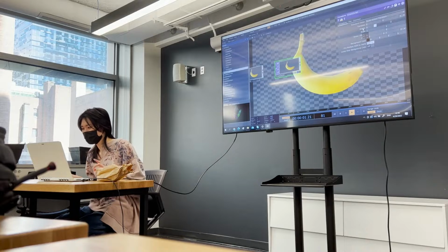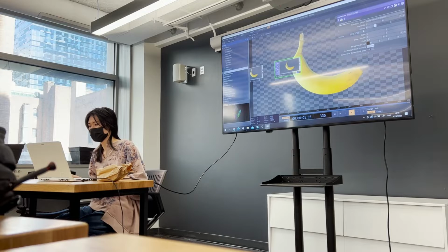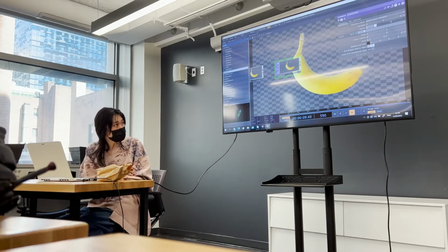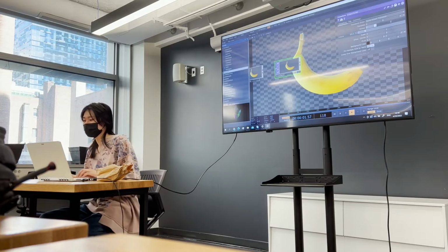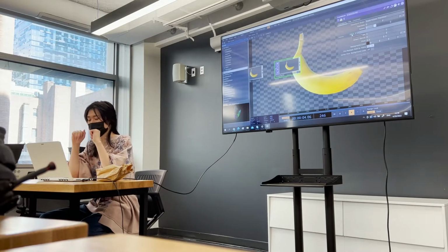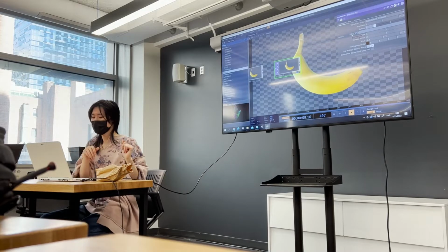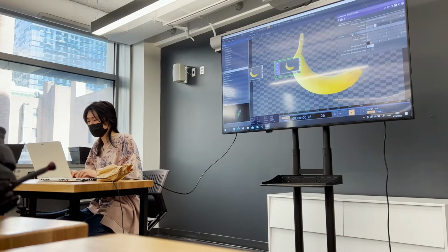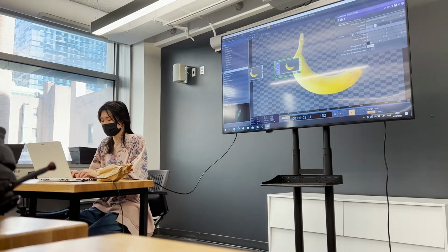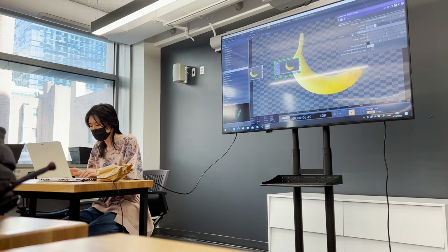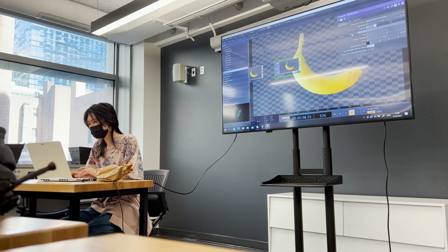Another thing is that if you click on, for example, the rotation, you can have this drop-down menu, which is a bigger window for you to type in stuff. Here you can type in not only numbers, but also expressions in Python. For example, one of the most commonly used ones is absTime, with T capitalized in camel case, dot seconds.